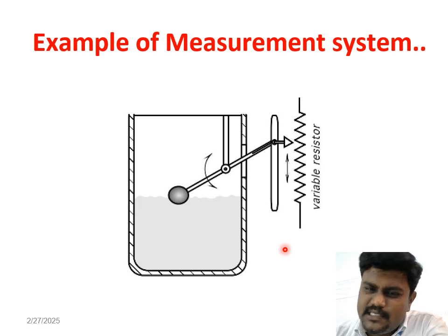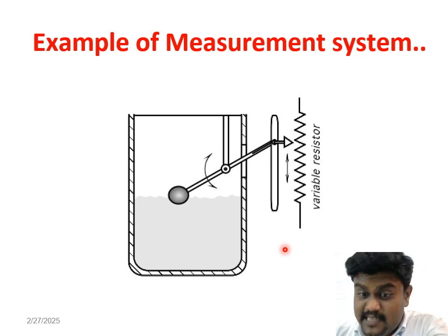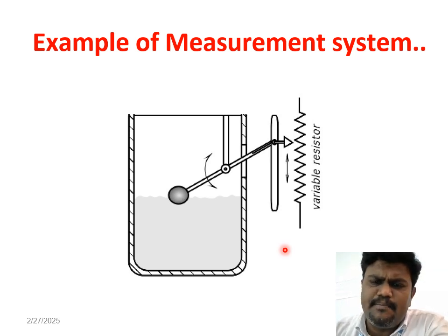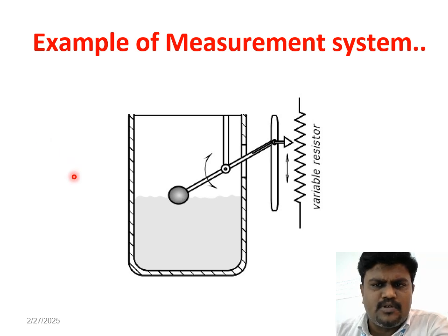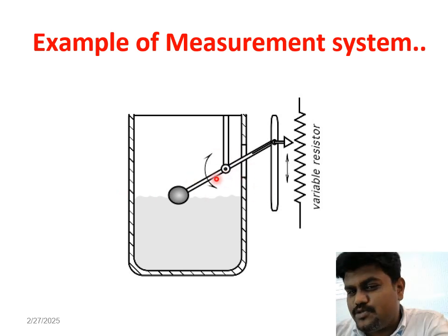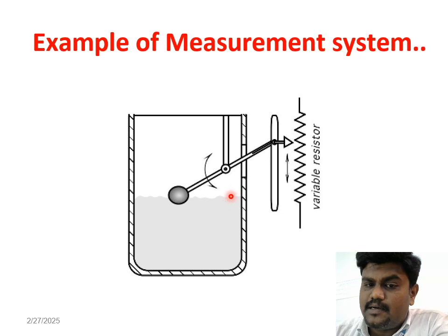water floating system, or water tank level indicator, you could say. We could often see this sort of mechanical floating based measurement system in our bathroom flush tank. When you open the lid of your flush tank, you could see a float which is attached to a pivot, which follows the level of water filled in.